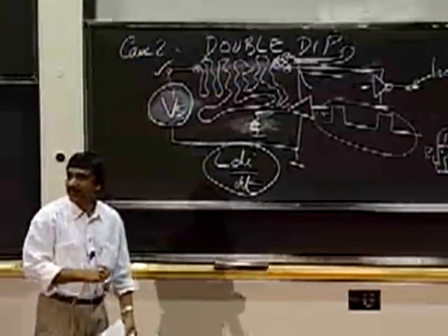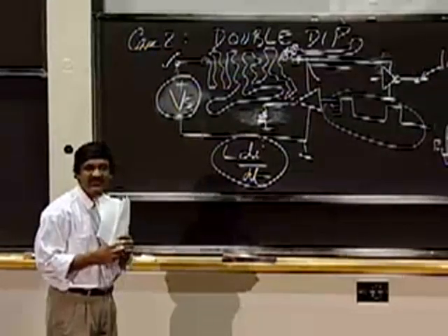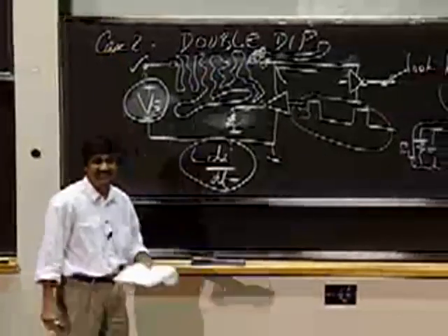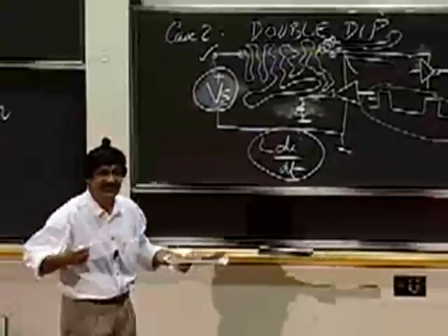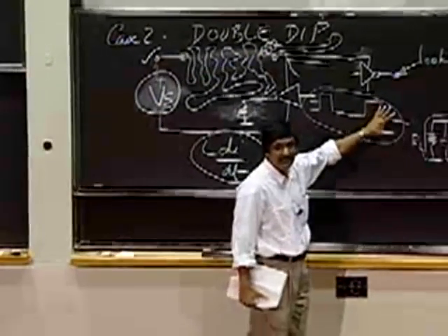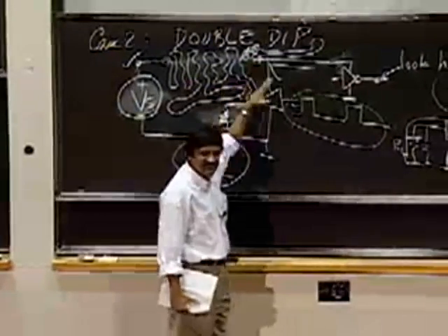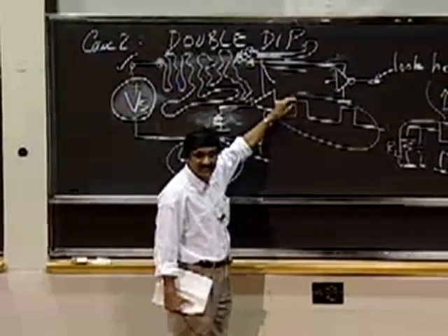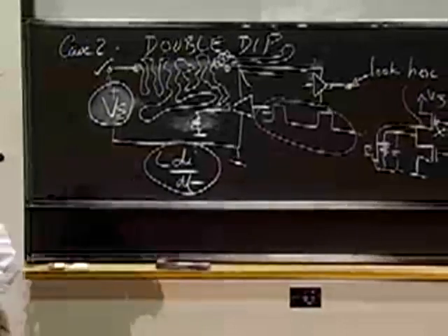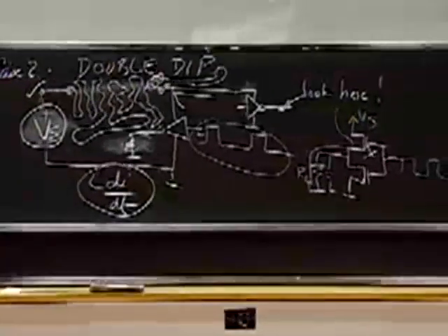Our own David Perreault, who is doing one of our sections, is one of the world's experts in this field. Something as simple as how do I get 1 volt in a stable manner to every single device on my chip is a hard problem. Now you have to begin treating your power supply connections much like RLC circuits. And you have to solve some hard problems to be able to simply distribute power decently throughout your circuit.